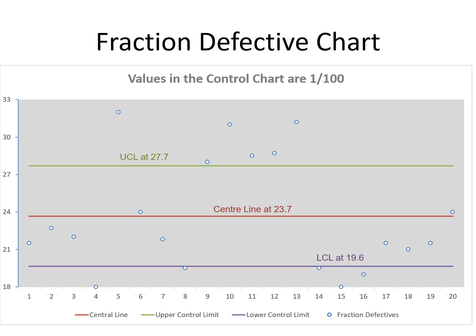For the sake of convenience, the red line is the standard line, the green one as shown here in this graph is the upper control limit, and the blue one is the lower control limit. So in the first, second, third the process is in control. In fourth it has gone out of control, again some adjustment might have been done. In fifth it has gone way beyond the upper control limit, and then it has come back to near the standard in the sixth, and so on.